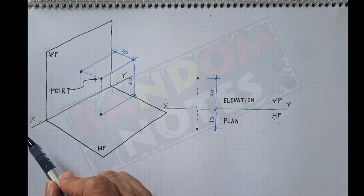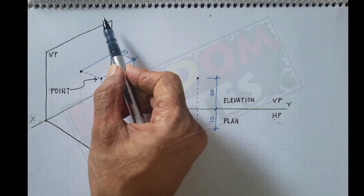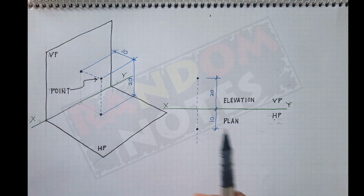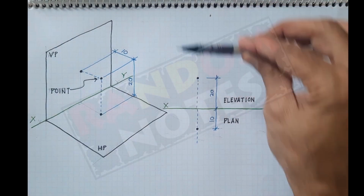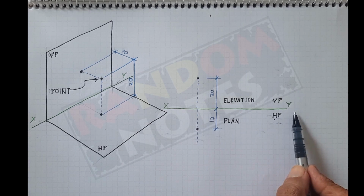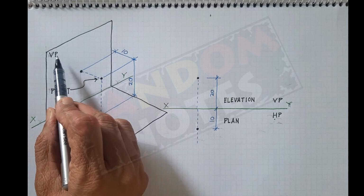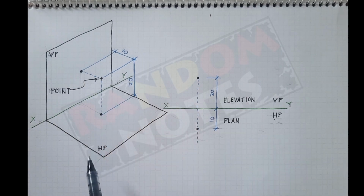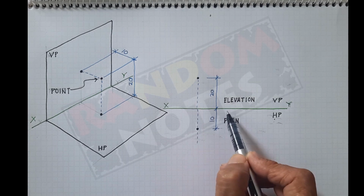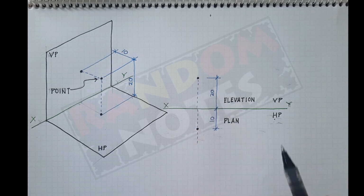Let us revise. This is the XY plane around which this is the horizontal plane, this is the vertical plane. We have opened this vertical plane, made it straight. So now we have vertical plane above and the horizontal plane below. This is the XY line which is similar to this. The point is 10 mm away from the vertical plane and 20 mm away from the horizontal plane. So I took any one of the dimensions. From the horizontal plane I took 20 mm and made this point.